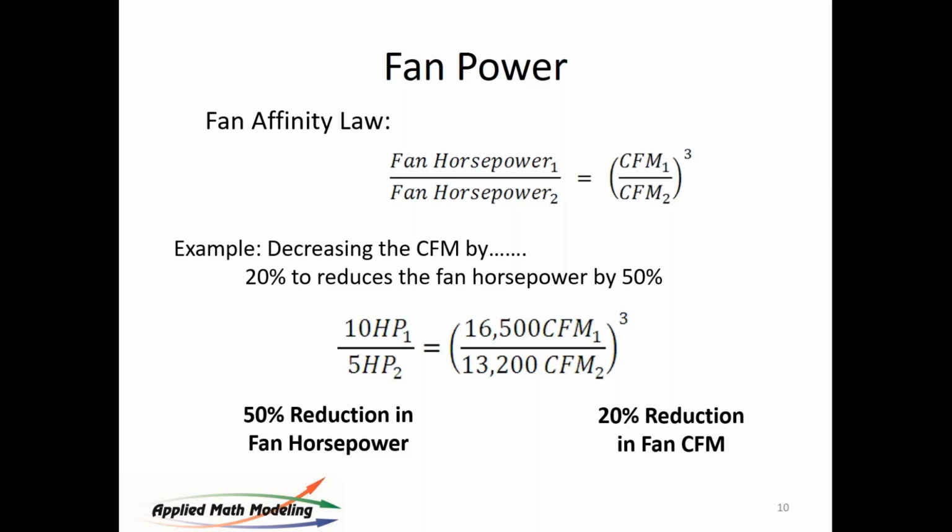So it's important to understand that new horsepower is equal to old horsepower divided by the ratio of the change in CFM or RPM, either one. And RPM is hopefully correlated directly to CFM, assuming your pressure is not too high across the fan. So that's an important one to understand.